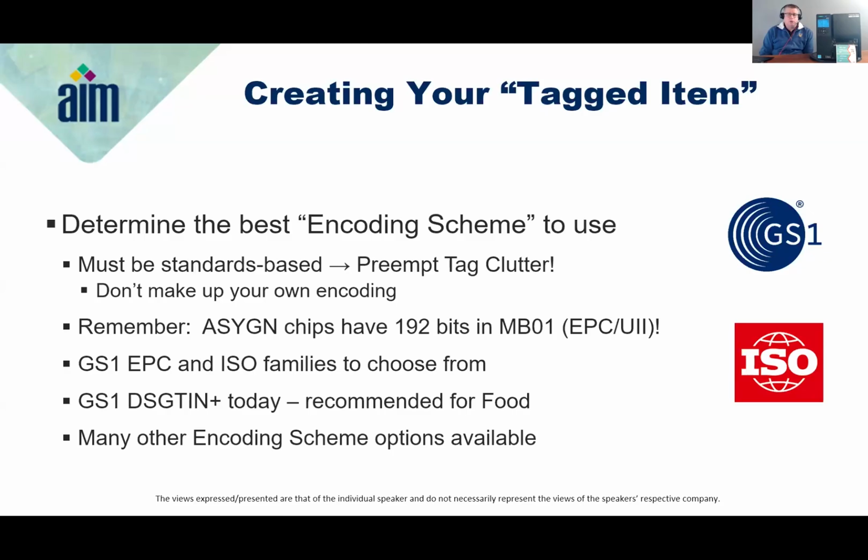What you cannot control is tags entering your reading environment. So let's say you have your meat packing facility and everything's working fine one day, but then the next day a package arrives from UPS, and that UPS box has an RFID label on it, and inside the UPS box are 50 coffee mugs that your marketing department ordered, and every one of those fancy coffee mugs has an RFID tag. Well, that box with all those coffee mugs could be in your read zone and could cause tag clutter.